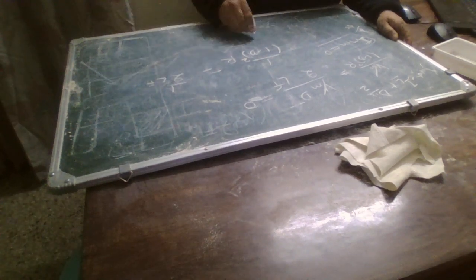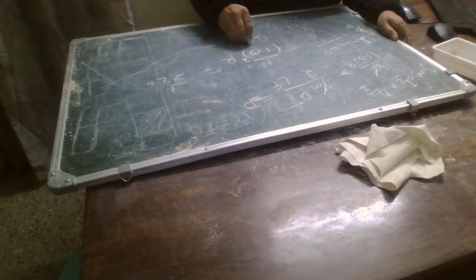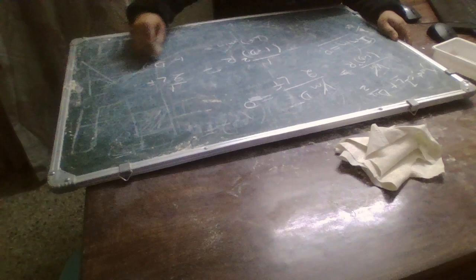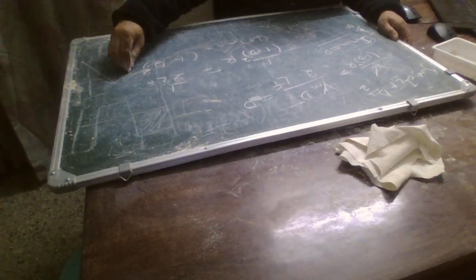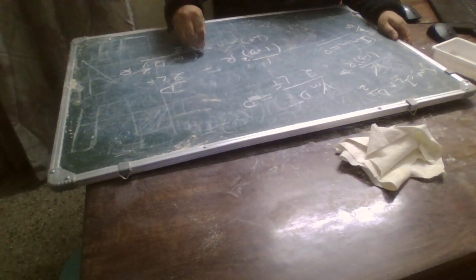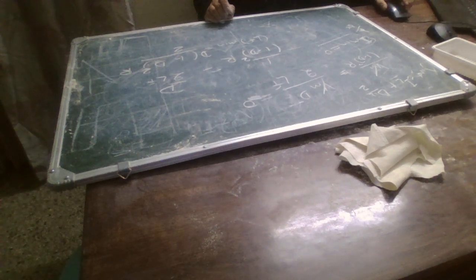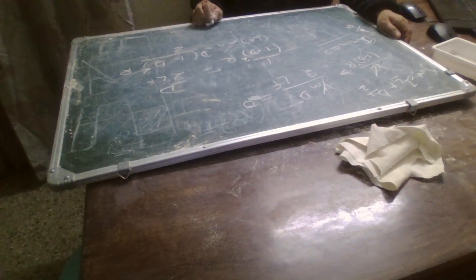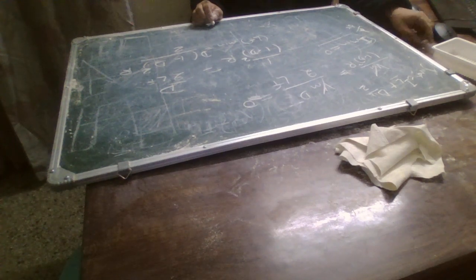Rearranging it, I am going to get LF minimum equal to 1 minus D the whole square R upon 2, and D would be there. So again we have got the minimum. This should be the minimum inductance value and the minimum switching frequency, so that the converter continues to operate in the continuous mode, avoiding the boundary condition.